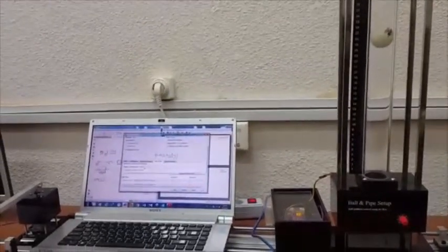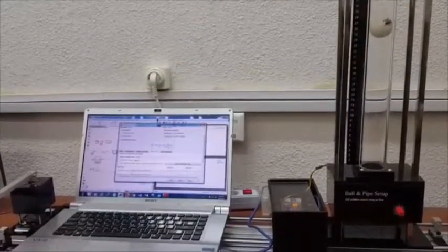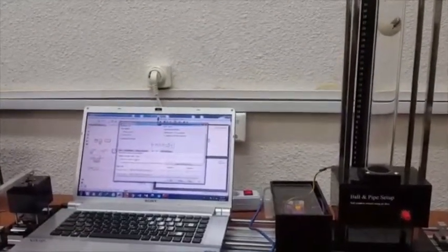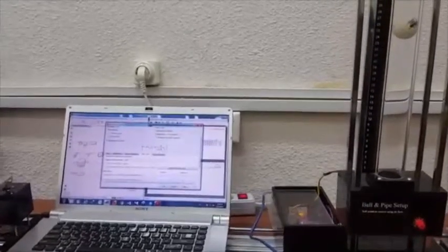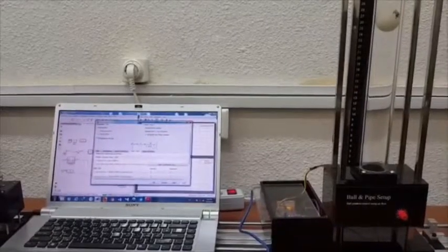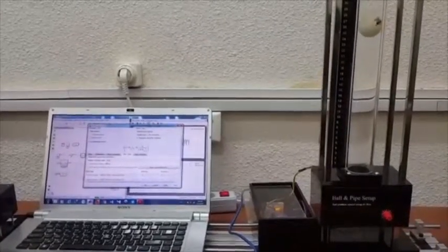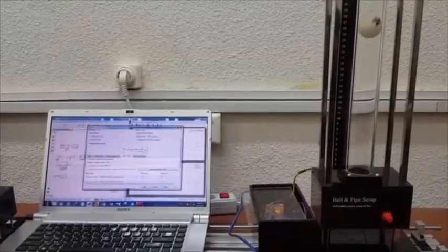As for the D term, I mean the derivative term, it yields a faster response and also increases the stability. And by decreasing the D, we have all terms vice versa. It means that it yields a slower response and a decrease in stability.